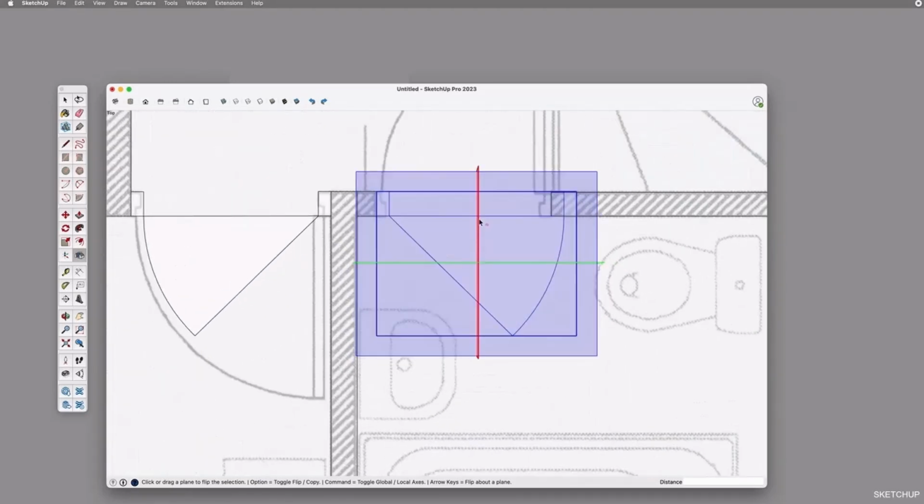In this case, the red axis will flip the object vertically from left to right, and the green axis horizontally from top to bottom. You can also use your left or right arrow key to navigate. Don't mind the blue axis for now, it will concern us later when we start using 3D. In 2D, we don't need it, since it will flip the symbol upside down, and we don't want that.